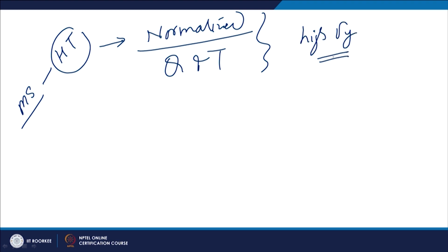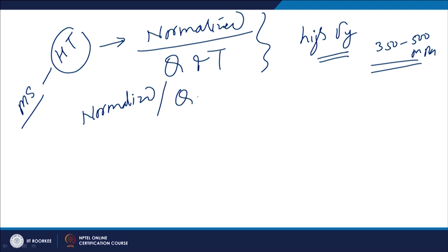strength, sigma y, can be ensured, so that they have a yield strength range from 350 to 550 MPa. Which means that it may be required to perform the welding in various heat treatment conditions like normalized or Q&T conditions.